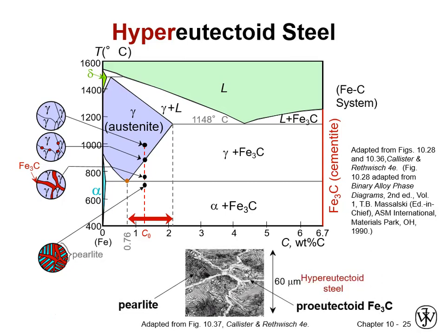So when we drop through the eutectoid temperature, all of the remaining austenite transforms into pearlite, and we get the microstructure that's shown schematically over on the left with the red and the aqua, and for real in a photomicrograph down in the center. And given the way the etch works, cementite and ferrite both etch white. So the white coating the grain boundaries is the pro-eutectoid cementite, which was shown in red in the schematics, and the remaining material obviously is pearlite.